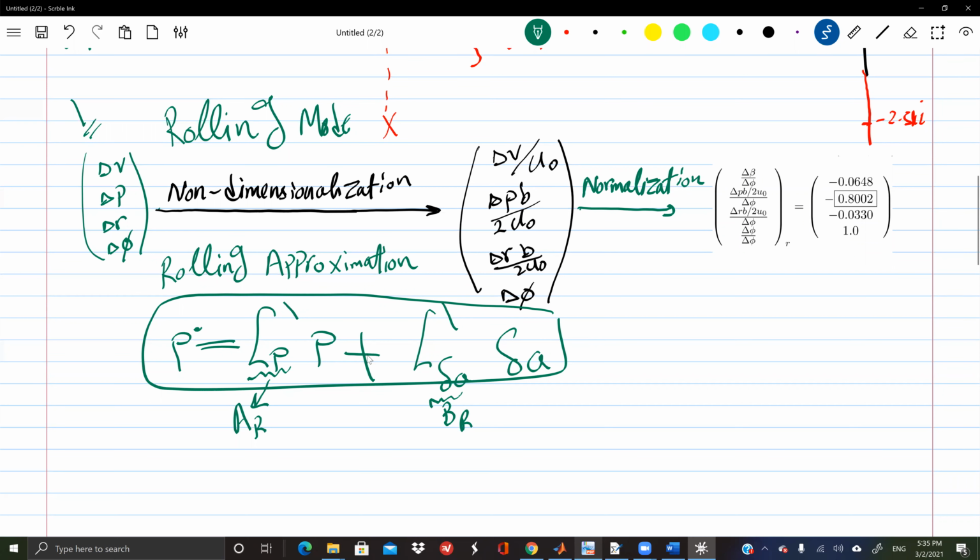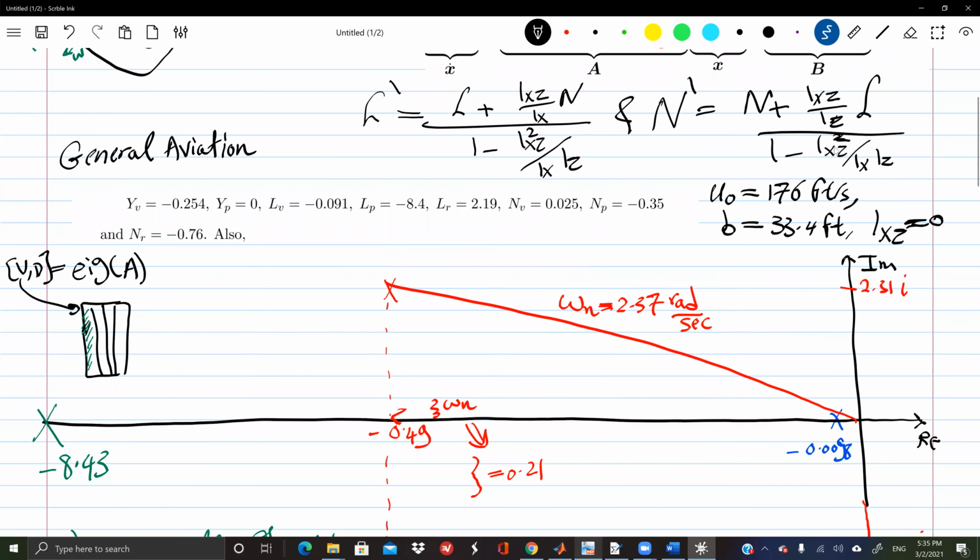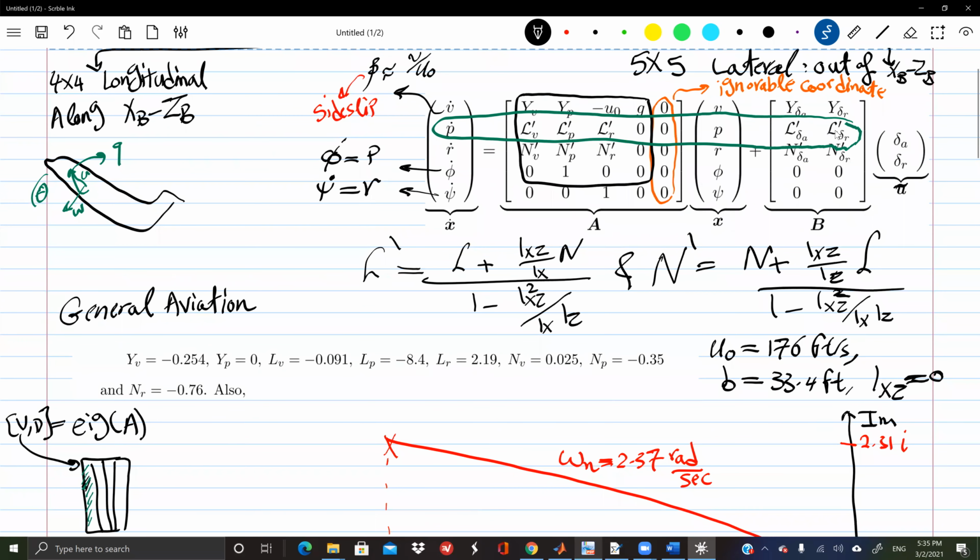Any question about that? Did we exclude the second input, delta rudder? You don't need to, but there is no need to have two inputs for one state. Of course, this is over-actuation. And if I'm going to pick one, which one should I pick, the aileron or rudder, for controlling the roll motion? It's indeed the aileron, right? This is why we have the aileron on the airplane from the beginning, just to control the roll motion. It's a good question.